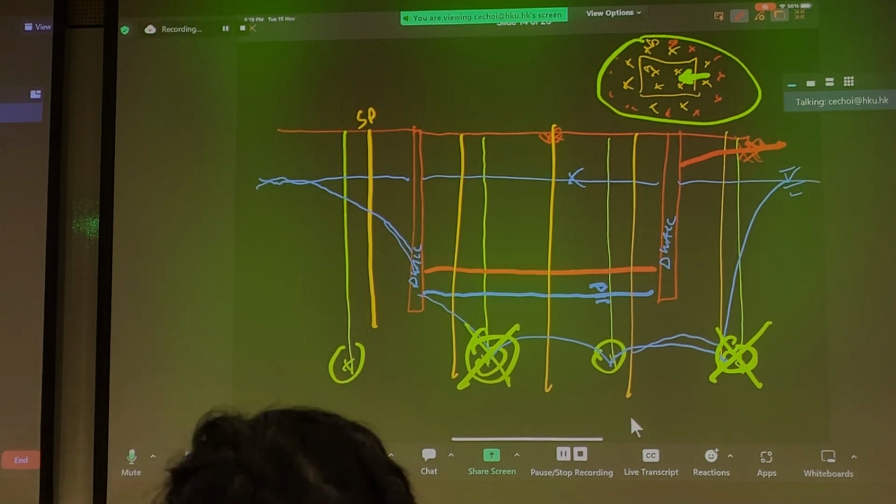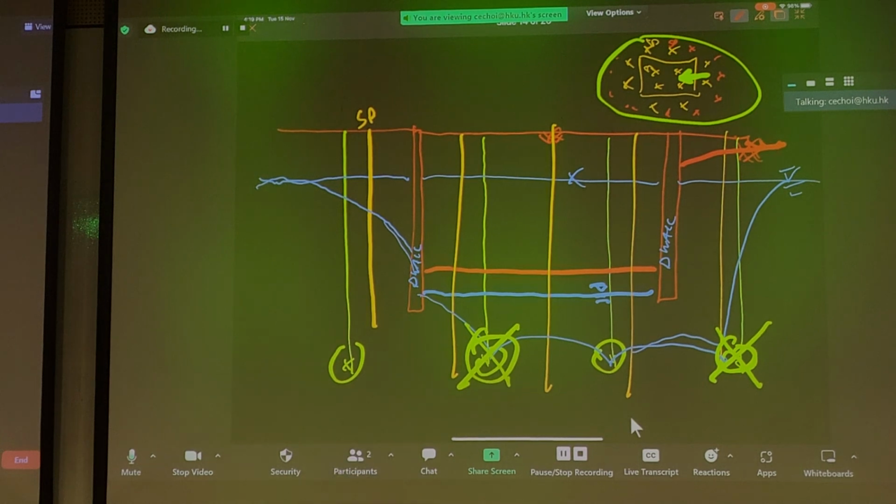So this is what we refer to as a pumping test. Any cofferdam inside a place that we need to dewater, we carry out a pumping test to do 3 things, as I mentioned, and I'll mention it again. First is, can we draw down to the required water level? Number 2, is the recharge freakishly fast, so we can't get people out? Number 3, what's the potential consolidation or subsidence caused outside of your excavation? So these are some things you need to consider when you carry out dewatering for cofferdam.